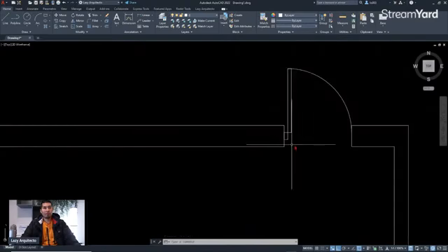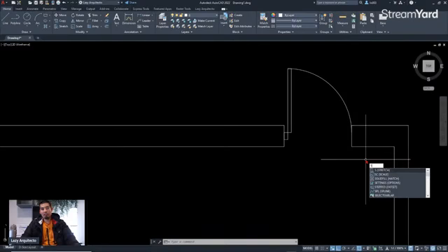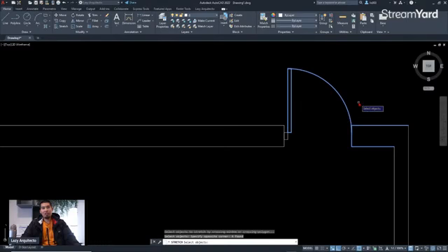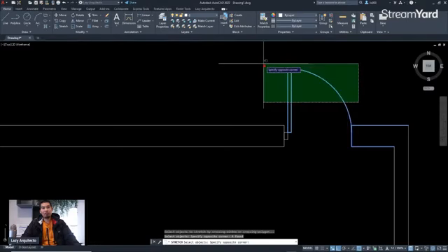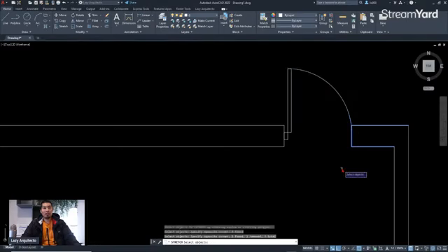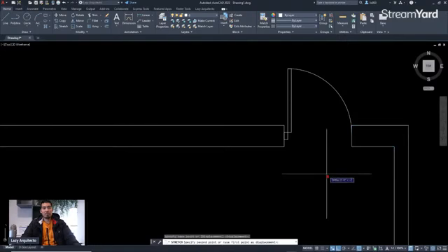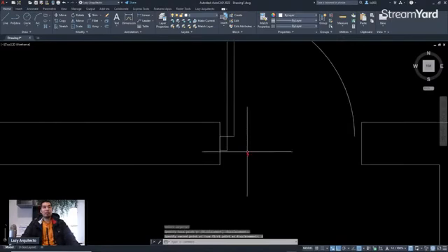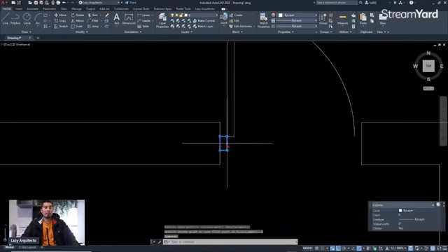So at this point, over here on this side, I'm gonna use again the stretch command to stretch this wall. Deselect with shift my door and then press enter. Click 2 inches to the side, press enter, and we're gonna need to copy this hinge to the other side.